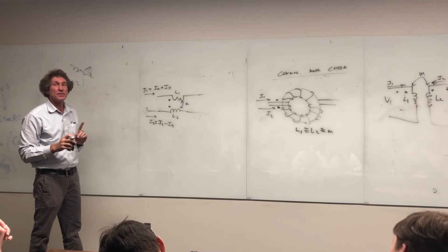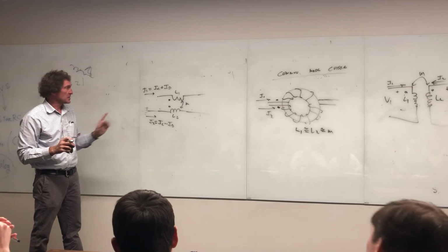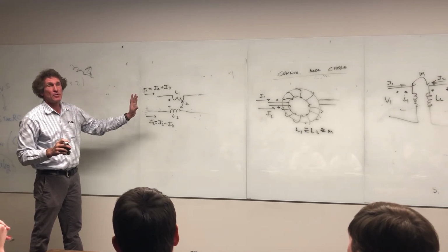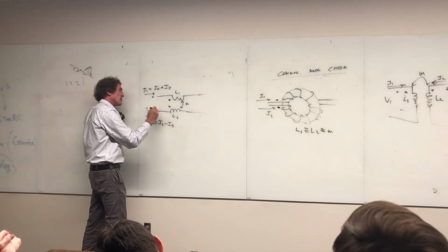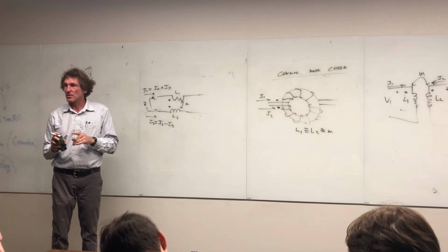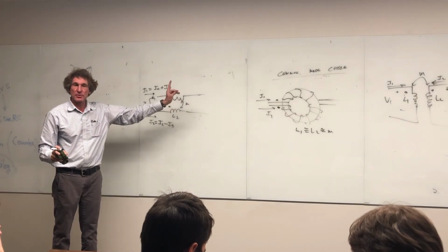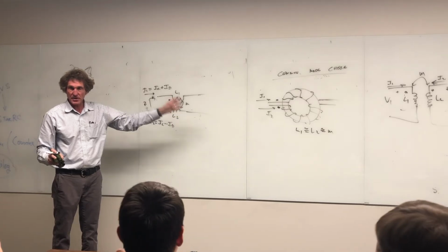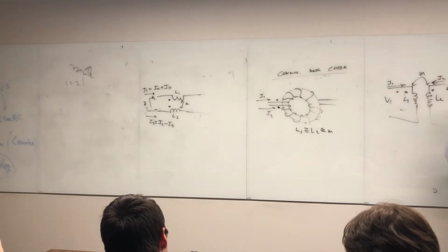But now what you can do is take a look at what happens as far as the impedance of this thing to a common mode current versus the impedance, and I'm looking right from here to here, right here, the impedance for common mode versus differential mode. Can you all see why I'm doing it? I'm not even going to put a load out there, I'm just going to put a short for now, all right? I want to show you the difference. So when I do that, I'm going to use this board. Here's what happens.